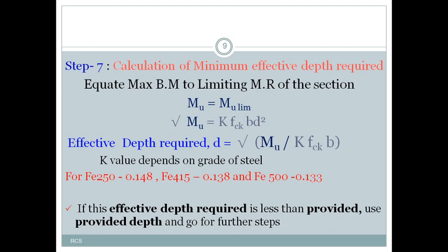Then our slab will bear the maximum bending moment coming onto it. So from this I can say that if the calculated depth required is less than the provided depth, provided meaning what we assumed earlier, use the provided depth and go for the next step.